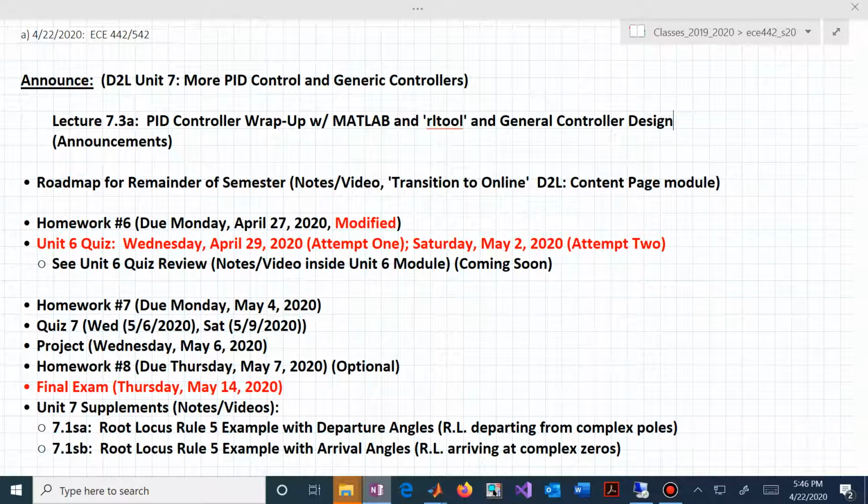And a non-minimum phase system is a system that has zeros outside the unit circle. And as we will see, if we don't already know, that actually is more challenging to design controllers when we have zeros sitting outside the unit circle, because we know that branches of our root locus will terminate on finite zeros, and if some of those zeros or one of those zeros is outside the unit circle, we know at least one branch is trying to migrate outside the unit circle as the gain k is increased.